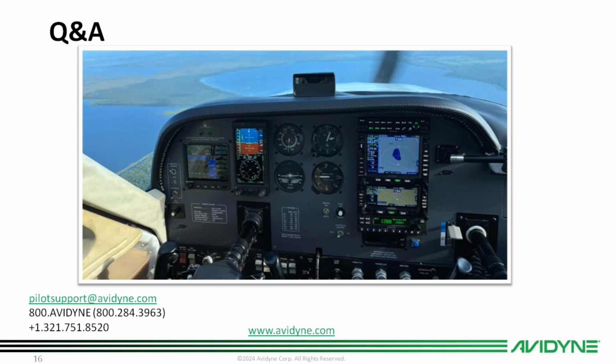Okay, thank you, Will. I have a GNS 430 as a number 2 connected to an Aspen Pro Max. Any changes with those connections? There should be no changes with the connections, assuming that you're having air data go to the GNS. That should already be wired to that tray. So it just might be some configuration changes, a little bit different, but most configurations from the GNS do follow the IFD. But yeah, there should not be any problems with that at all.